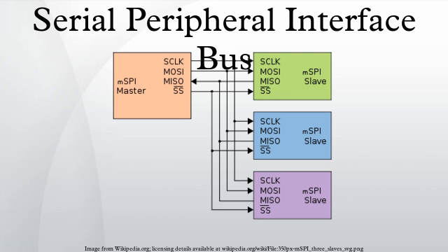Some Microwire chips also support a 3-wire mode, which fits neatly with the restriction to half-duplex. Microwire Plus is an enhancement of Microwire and features full duplex communication and support for SPI mode 0 and 1. There was no specified improvement in serial clock speed.